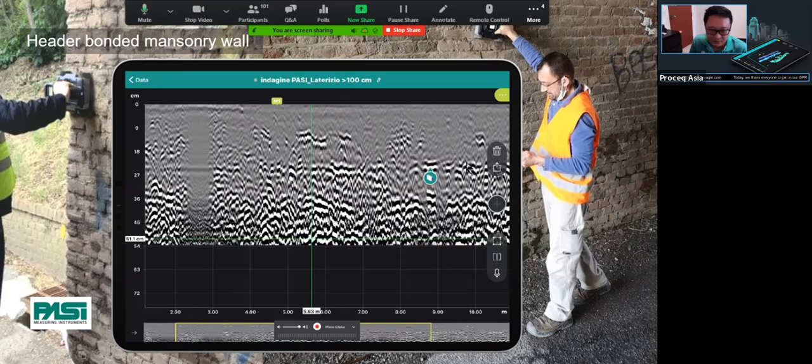The problem in this 2 to 3 meter section is actually higher moisture, I suspect. And we can see some reflector from the brick itself. I'd like to say that's half of the brick, maybe the brick is broken halfway. So overall, you can use this kind of GPR diagram to look at and analyze your data.